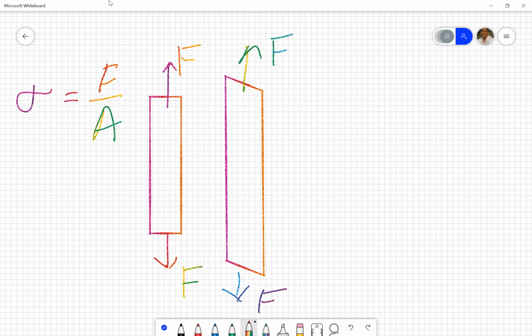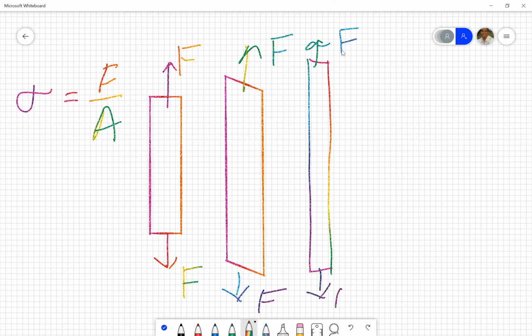That is stress. But the question is, when the load is applied continuously, the elongation goes on increasing. When the elongation increases, there is a shape change. That means the deformation increases. The dimension of the material will decrease. The dimension means the area will change continuously. With the increase in elongation, the area will change continuously. But when we are drawing the engineering stress strain diagram, we are not focusing on the change in area. Always we write this equation. In engineering stress strain diagram, always we write this equation, stress as force per unit area, resisting force per unit area.